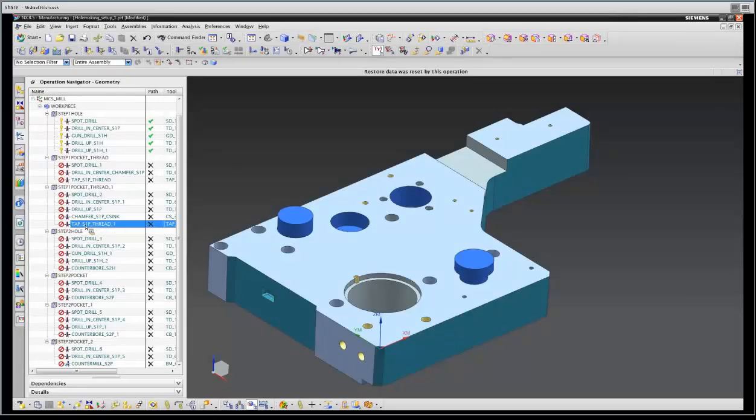But this rule-based approach, or if we were to essentially do the same thing and use the template-based approach, give us very similar results, different ways to control the output that we get. With the template-based, it's essentially going into an NX manufacturing file that's been designated as a template and setting the way we want things to work in there and making sure that we have some of the rules to work right. But in the full feature-based machining, then we go into the knowledge-based rules, and that's where we would edit if we wanted to change the process in any of those.